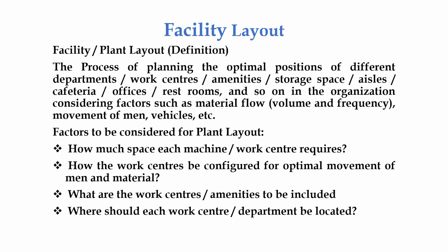Then, how work centers are to be configured for optimal movement of men and material. This depends on the sequence of operations and the number of machines, whether we follow a product layout, process layout, or some other type of layout. Accordingly, how many work centers are required and how best we can arrange facilities for movement of men or material.